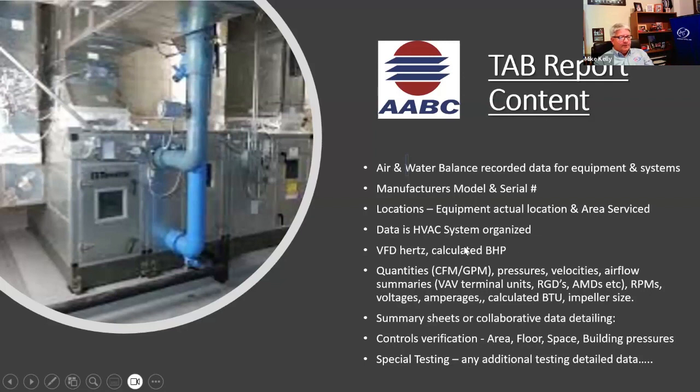What's the summary of the air handling units operating at, say, 92% of design? All outlets have been balanced within 96%. We're establishing that the unit has 6% duct leakage, although everything was duct pressure tested. Those summary sheets and collaborative data detailing should be listed out and explained, from a good balancing perspective, why your system is the way it is.